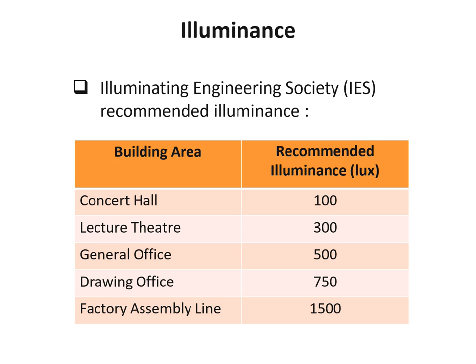Okay, so you can also provide maybe two different levels, because if you provide 750 across the board, the room is very well lit, but there will be certain fatigue that comes along in that kind of setup. So we can light the general office area at one lux level, a gentler lux level, maybe 300 to 400, and then for the general workstations, it might come with their individual lamps that bring up the illuminance level to 750. So there are many different levels that we can play around with.